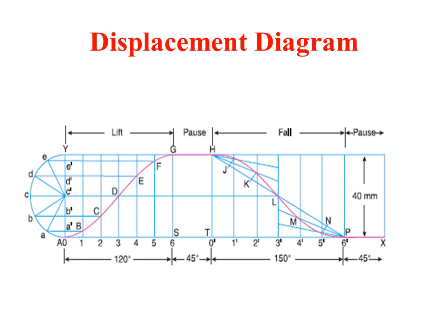Here the midpoint is 3 dash. Take this point and take this vertical line. Now this vertical line 3 dash has to be divided again into an equal number of even parts, 6 as we have taken earlier. So divide this vertical line into 6 parts.